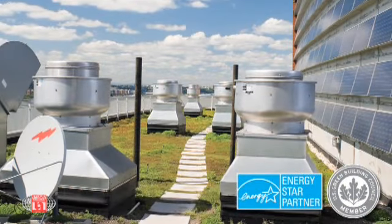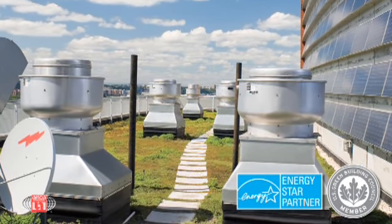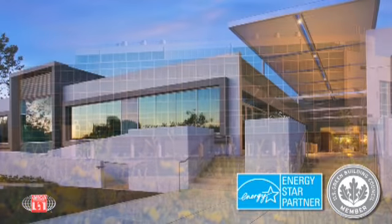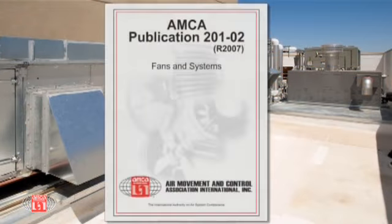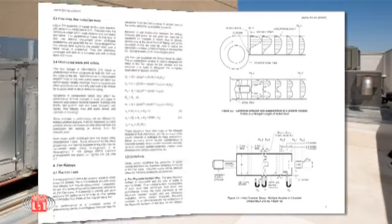System effects can be quantified, however, in the new world order of building green, high-efficiency building designs and net zero energy use buildings. The system effect in new air system designs must be avoided. For older and currently built systems, AMCA Publication 201 provides a means for evaluating the system effect magnitude to identify sources for energy reductions through system improvements.